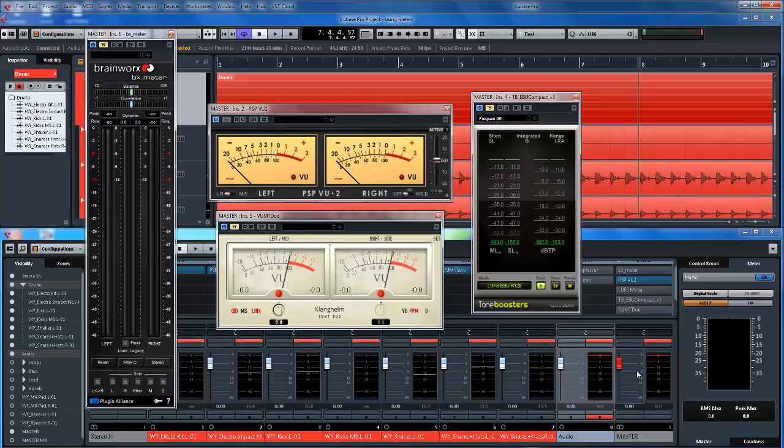This, let's say it's now at 4 milliseconds, but here's the problem. Whereas the rise is 4 milliseconds, the fall is 1.5 seconds. That's ludicrous. But there was a reason for that. At the time when it was developed, it was so that we could actually see the value sustained on the meter, so we could actually read it. If we had a shorter or a much shorter fall time, it would barely have time to register.